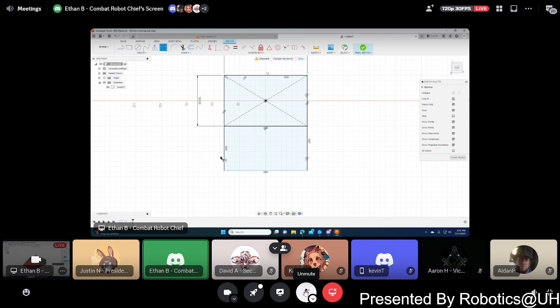This I want to dimension where it would have a proper distance. I'm gonna do 40 millimeters, and I will create a line here that goes on to connect with this shape. I will use the mirror tool, which actually first I'll create a line as a reference because that helps. I'll just put it here. Here's a way to make a reference line. You press the line that you want to make a reference line and press X. That makes it so that it doesn't interfere with other things when you don't want it to, and you can use it for what I'm about to show you.